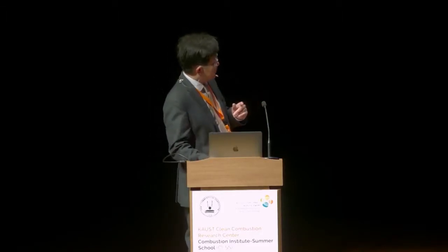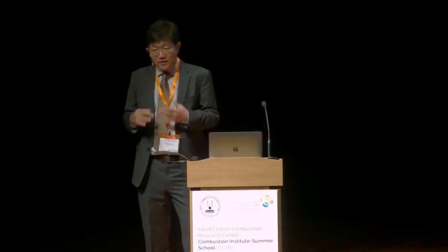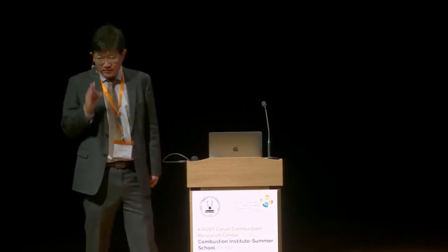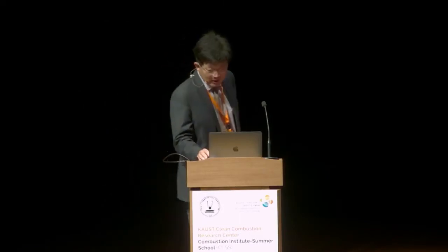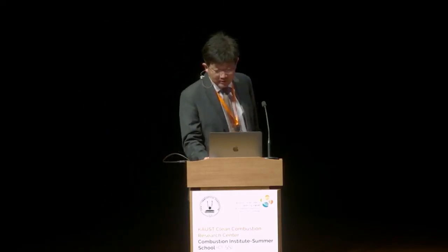So in that sense, an infinite Zeldovich number limit, like the flame sheet limit in non-premixed flame, is not valid, even conceptually. You cannot imagine a premixed flame that has an infinite chemical reaction rate. The chemical reaction rate is what dictates the flame speed, and it has to be finite always. It's a very important concept to remember in understanding combustion dynamics.